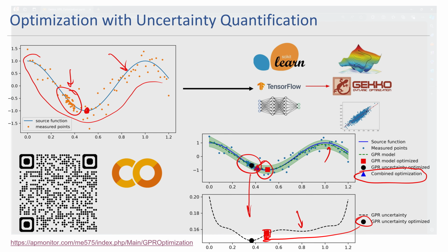Here's another example built into Gekko, from gekko import support. You create a new agent, and then you can ask that agent something like create an example optimization with Python Gekko. So you don't have to leave the Jupyter Notebook environment in order to be able to get support for your application. And here you can see the problem is solved. If I put display equals false, it doesn't show the solver output, and I can solve locally as well.